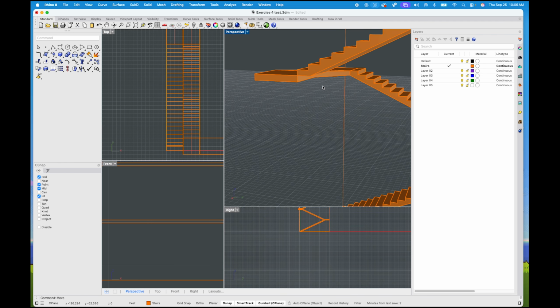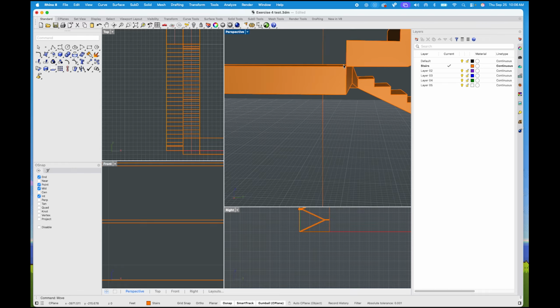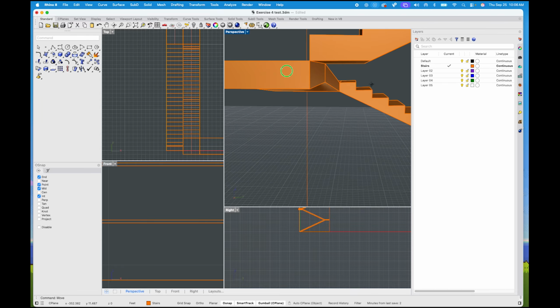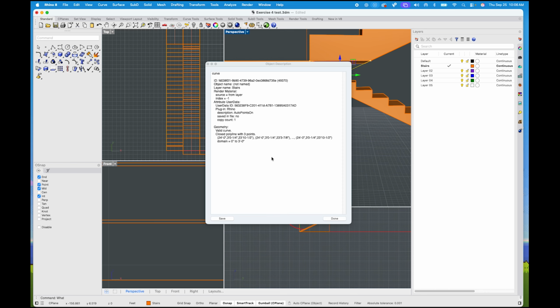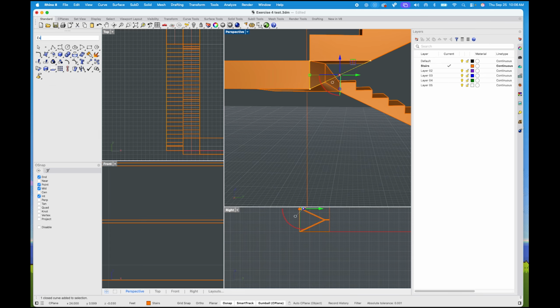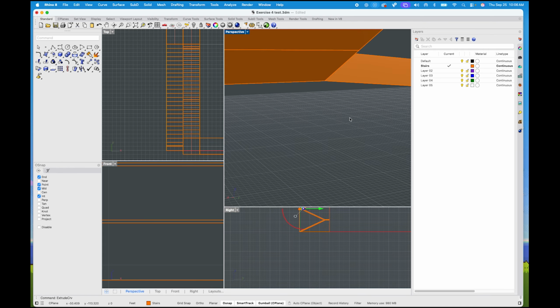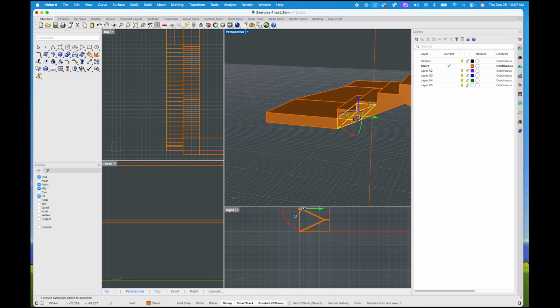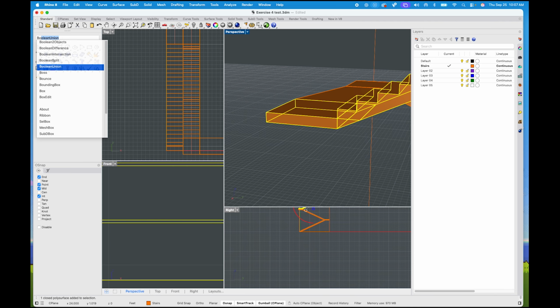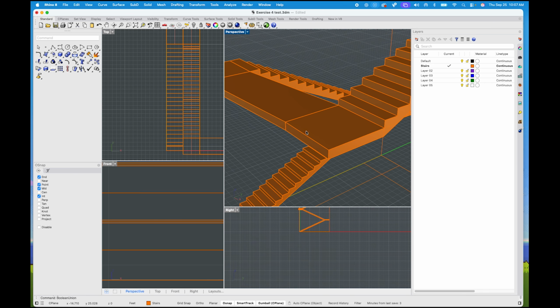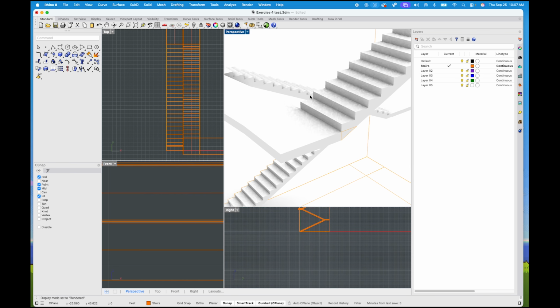But another thing we can do is actually add on to it. So this is usually what we do for stairs, is have this magical situation where things are joined at the edge, which is just a little unrealistic. So what we could do is, of course, fill that in. So I'll use a polyline and basically just trace that triangle. Sweet. I will make sure that it's closed, and I'll type in what, and yeah, it'll say valid curve, closed polyline with 3 points. Wonderful. Because I don't want to sit there all day and find out. Extrude curve, and obviously go to the other side. Well, not that far, but to the other side. Voila. We can sort of fill those blocks in as well, and we could further use them. I could join them all together, and we should get a better piece. Voila. Right? Definitely not bad. And potentially, eventually, I can do that to all of these pieces, right? That way, when I, of course, go into a rendered mode, it starts to look pretty smooth and pretty nice.